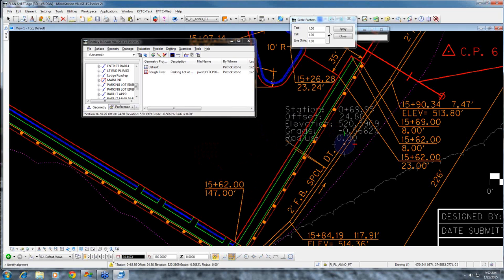So if you want to activate an alignment, you use the control and the data button. If you want to track between them, you just hover over it and data point to it. And then if you want to get back to the alignment, you just reset out one click. Is that clear as mud?